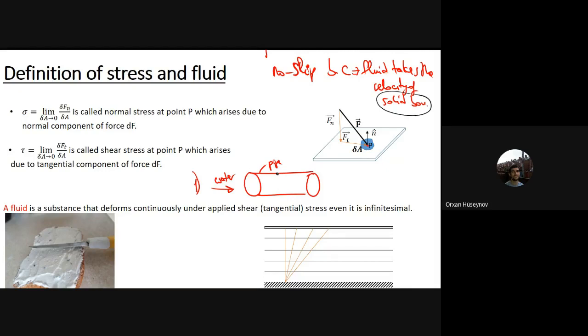The solid boundary is here, and the solid boundary is here. The velocity of water at this solid boundary is 0. Water at the boundary doesn't move. So you can say that there is one layer of water inside the pipeline that is always there. It doesn't move forward, it doesn't move backwards, it is always there, at the location where it touches the solid boundary. This can be one example.